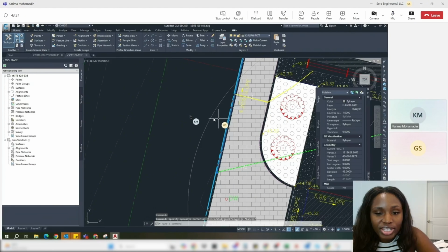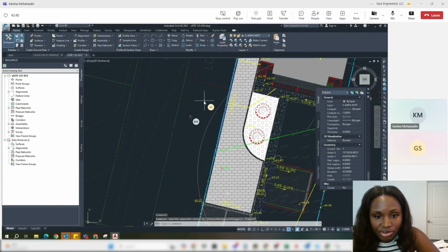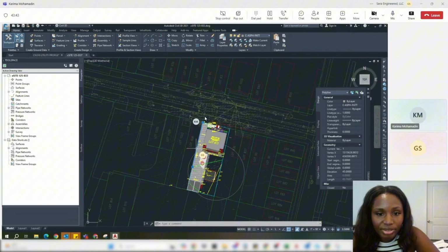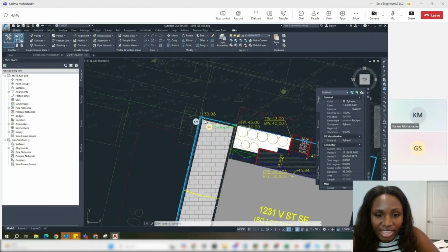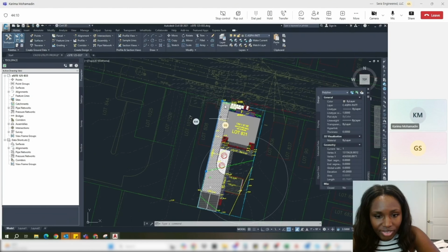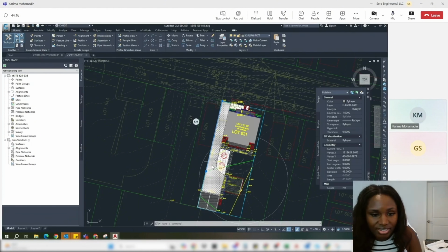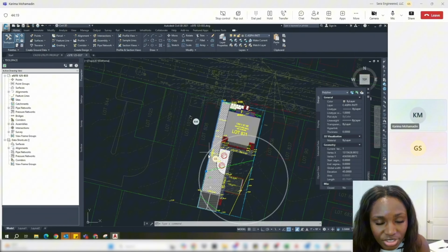And so if we change it to an infiltration trench, there are 2 more things we'd have to do. One, we would have to have an inlet at this low point, so that would have to be a trench drain. They'll be crossing in. It'll be a trench drain at this point. And once the water gets into the trench drain, it then goes into a filter, and then there's a pipe that's going to spread throughout the system, and it has rocks in it, and the water is just infiltrating down into the system.